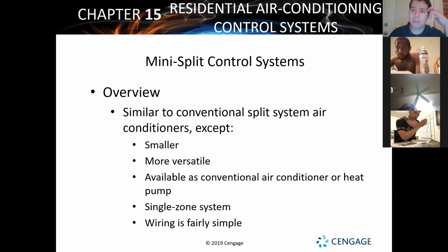So the mini split controls are pretty simple. You've got multiple styles of them. You can have them single zone or multi-zone. And the nice thing is they require no ductwork, zero. So mini splits are becoming popular. Again, I was talking about earlier, packaged units are really popular for older homes in Richmond because you can't fit ductwork into the walls, because the house was never meant to have ductwork. Mini splits are another popular option because you don't have to worry about ductwork. You don't have to think about it at all.